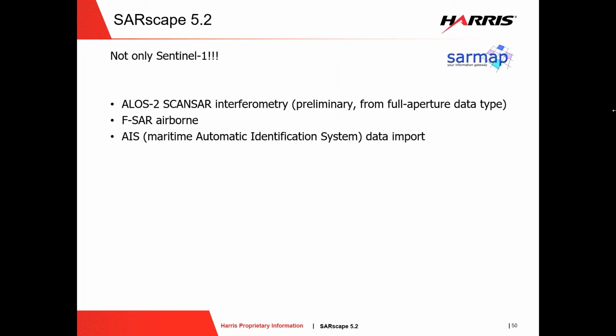ScanSAR interferometry package updated to allow you to generate interferograms for ALOS-2 ScanSAR data. In particular, if you are interested in this feature, you should use data processed in full aperture mode, not in burst mode. But with full aperture data, you can generate from ScanSAR acquisitions of PALSAR-2 very nice interferograms.